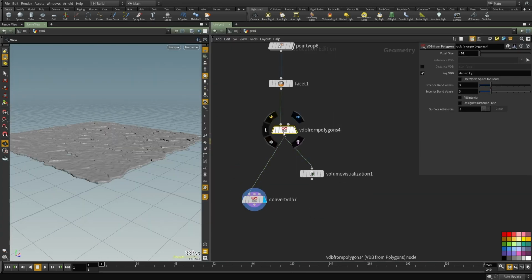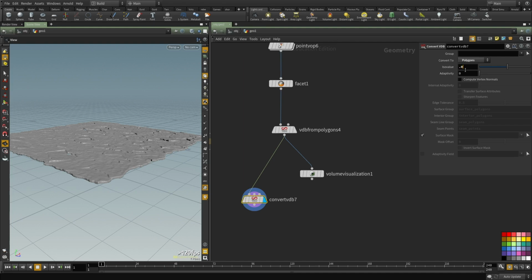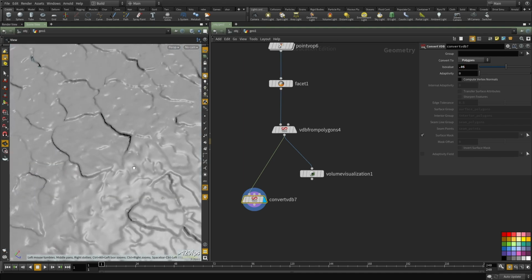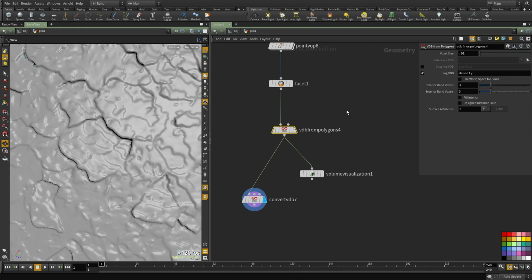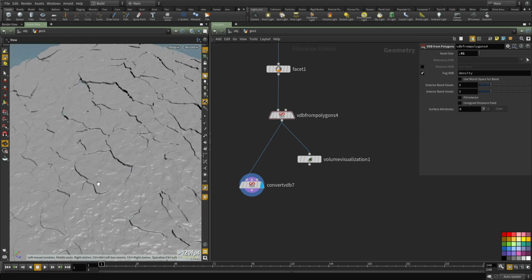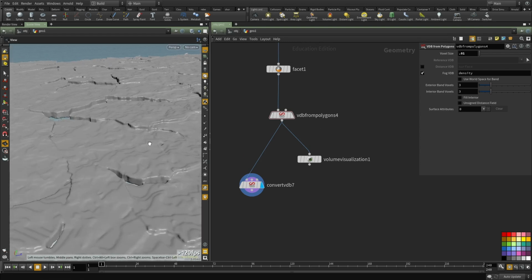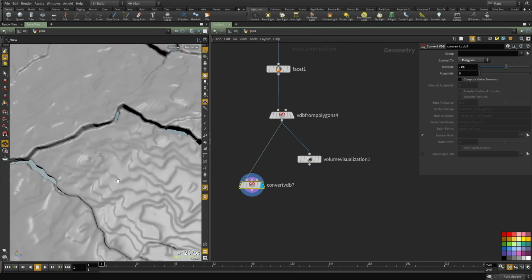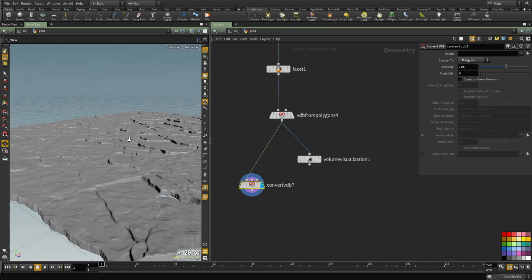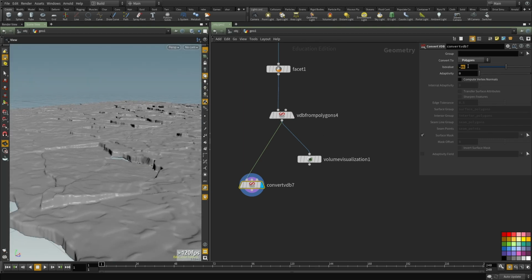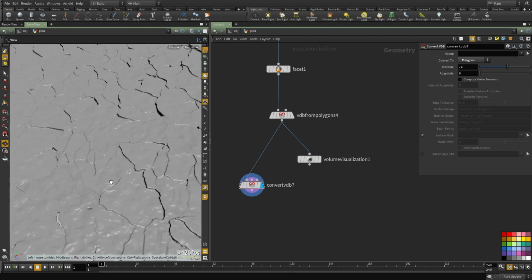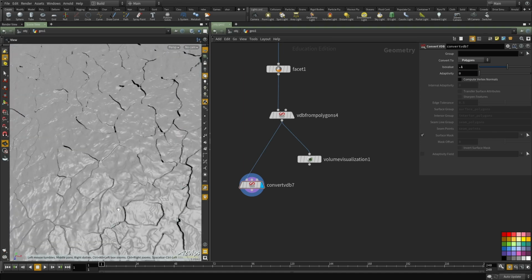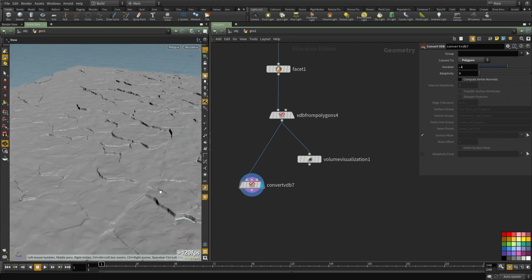Cool. So let's increase. It's very high res, so let's increase this to 0.05. Let's increase this a bit more, 0.1. I want to capture more details. Okay, cool. Now you can see, the more voxels, the slower it's going to be. We can see we're getting a lot of details. Now it's getting this stepping effect, and the reason for that is because we're reaching the limit of the data. That's how much data we have. So we need to be a little bit careful with that. But so far, in all the tests I've done, that stepping effect with rocks actually really helps.